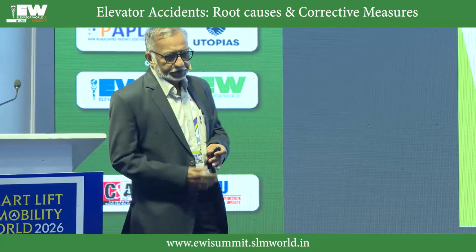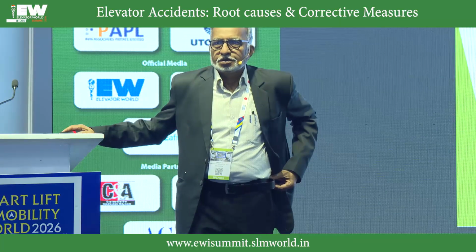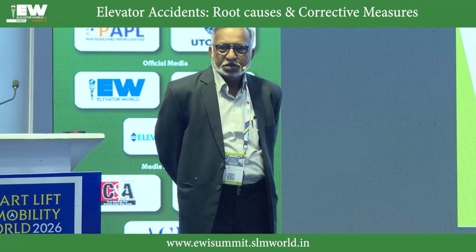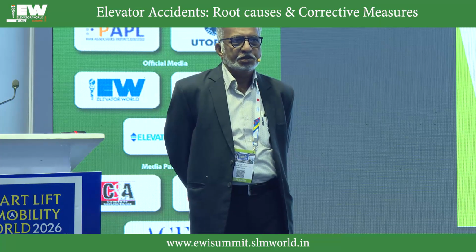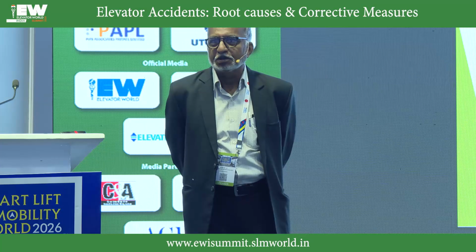Now the question is, how can the landing door become open in the absence of the lift? If the lift is not there and the door is open, then it is you and me who are responsible. And we are from the industry, we are purely responsible. The reason could be lock shot, control failure, or lock failure. So during every maintenance, we have to check all the locks seriously, as if you are traveling in the elevator and your life is involved.